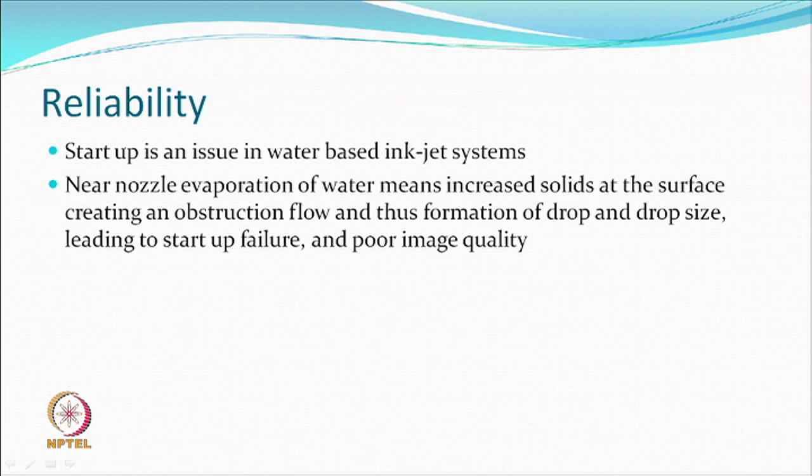And this happens because there is near-nozzle evaporation of water, which means solids at the surfaces are going to be deposited. It will cause an obstruction of flow and formation of a drop size, leading to a startup failure, and then of course poor image quality.